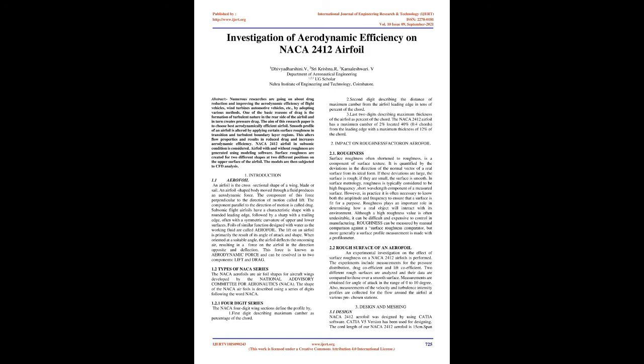The lift on an airfoil is primarily the result of its angle of attack and shape. When oriented at a suitable angle, the airfoil deflects the oncoming air, resulting in a force on the airfoil in the direction opposite the deflection. This force is known as aerodynamic force and can be resolved into two components, lift and drag.